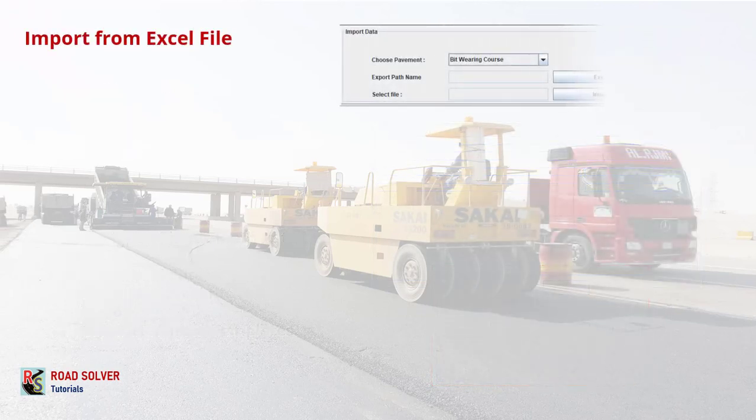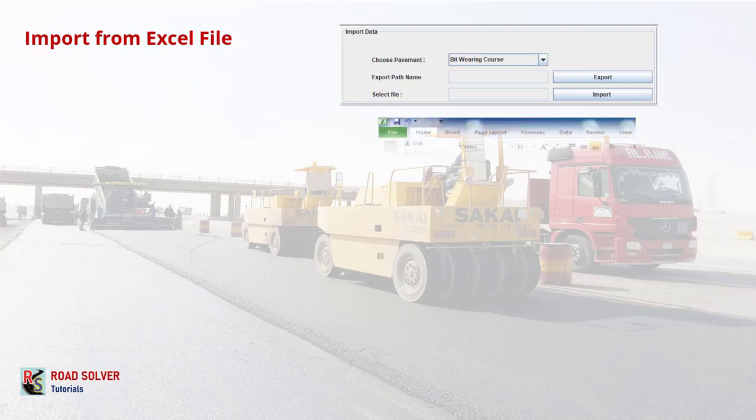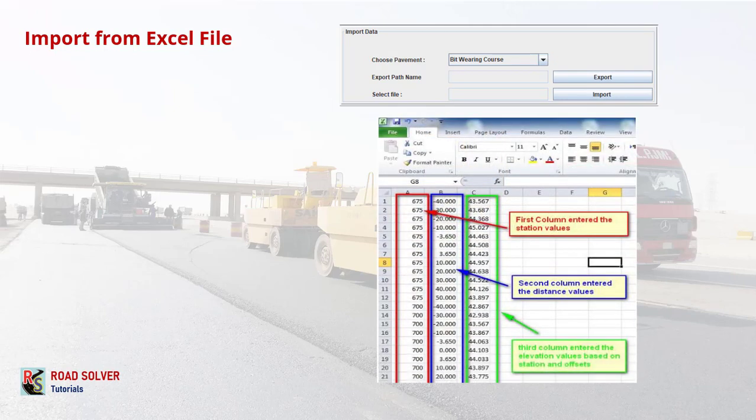Now the first thing is import from an Excel file. The format is station, offset, and elevation. You have to type all the levels like this, then save this as a CSV file format.